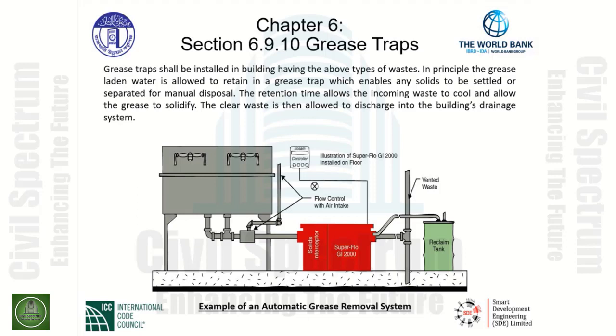Now, the retention time allows the incoming waste to cool. There is a compartment that captures the grease that has been solidified and thus allows clean water to move through another compartment, not contaminated by any grease. That is the function of a grease trap in general.